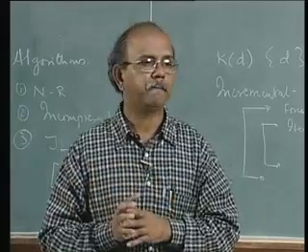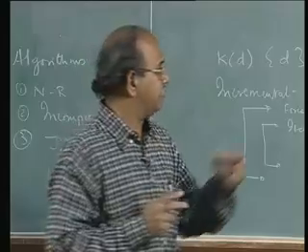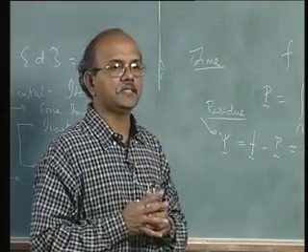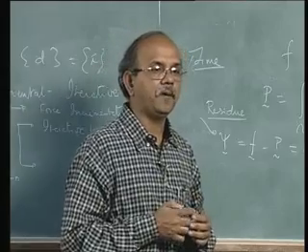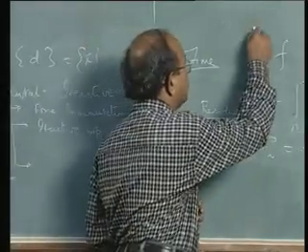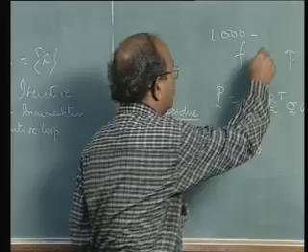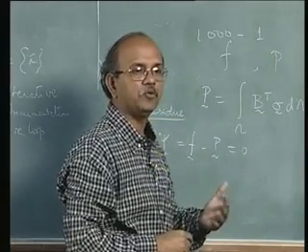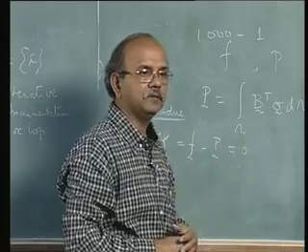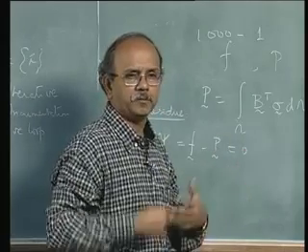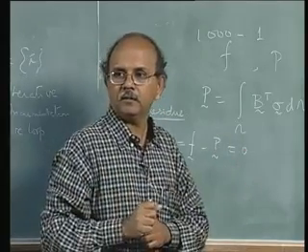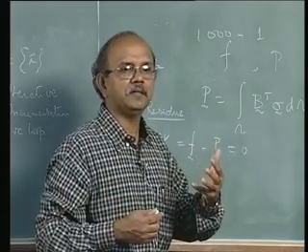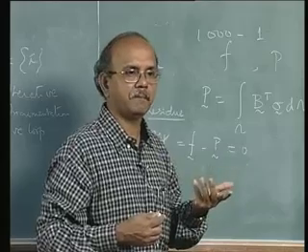It is just a pseudo time. So, in other words, time is a carrier of force. What do I mean? I can say, let me apply all the load in 1 second, say 1000 newtons in 1 second. Instead of saying that at every step you apply 100 Newton, which becomes cumbersome when you program it, what these softwares do is to say that increment it in terms of 0.1 second.